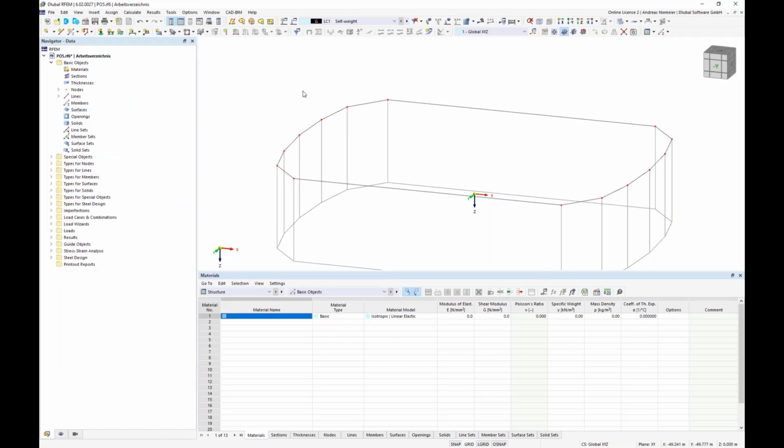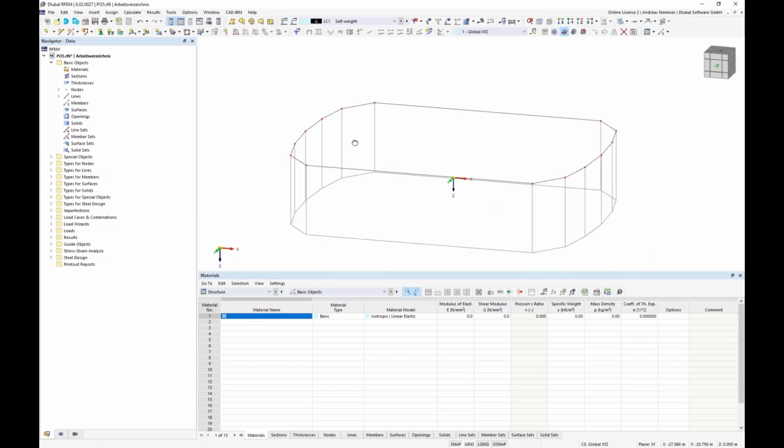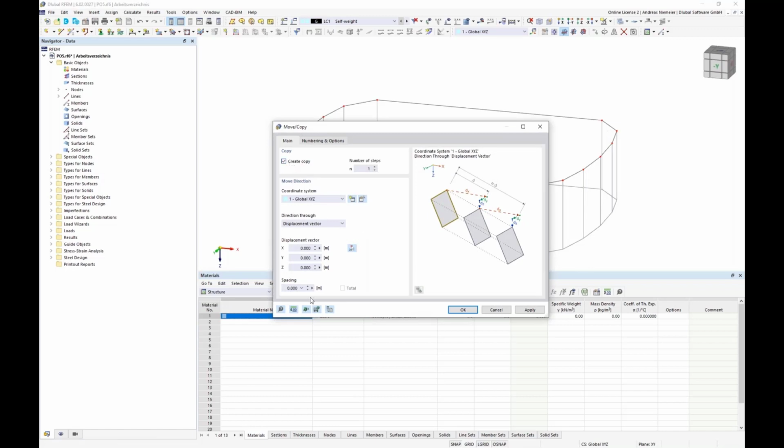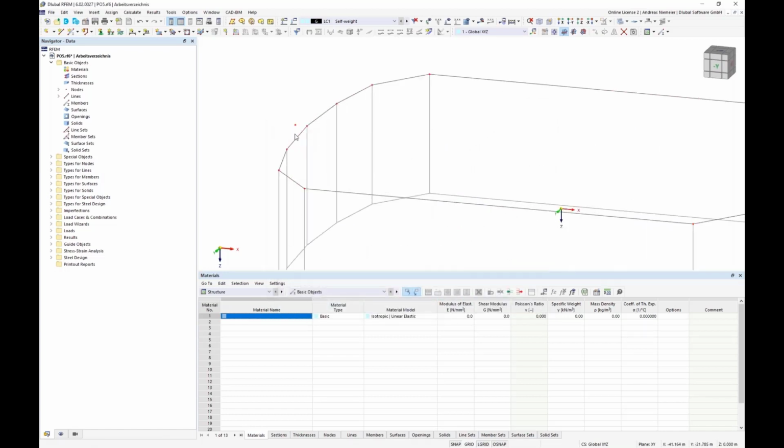Now let's take this geometry as the start condition, but as you also saw in the pictures, the roof is covering this building block a little bit. Therefore, we scale it up so that our roof really covers this block. Let's take a measurement, for example, 0.5 meter. I copy this node here with copy and use, for example, 1.5, and produce here such a control node which should be almost